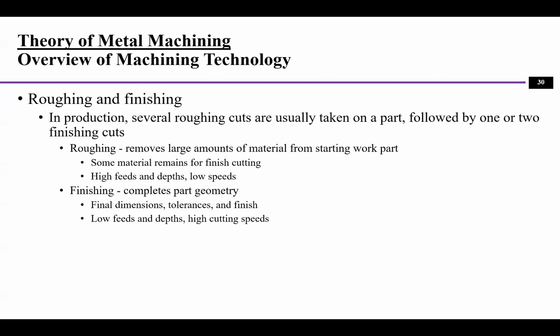Something to pay attention to is that during machining, we typically have a roughing process and also finishing, because the surface finish and the cycle time can be different during the operation. Why? When we have a raw workpiece, we usually start with the roughing process, which is to remove a large amount of material from the workpiece, so we can get really close to the finish, right?